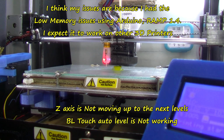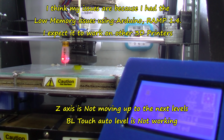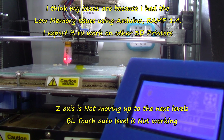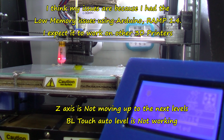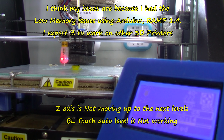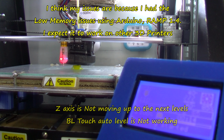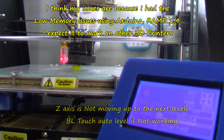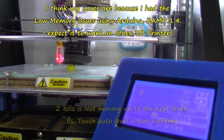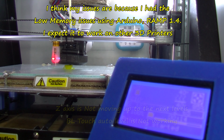I'm just crouching down to make sure it's not doing that already. Now remember, I do have a servo, I have a BL touch, I have the filament run out sensor, all on the same power supply here, basically. So those might be draining the power supply. Remembering it's just a small buck converter. It's not like a high powered buck converter, I don't believe. From 12 volts to 5 volts going in that pin.